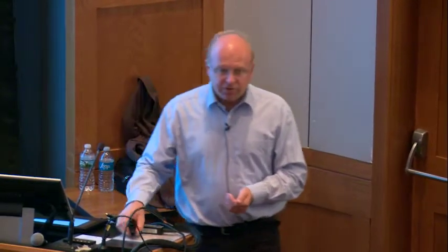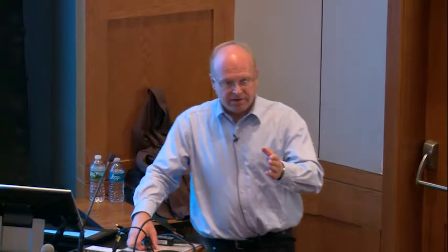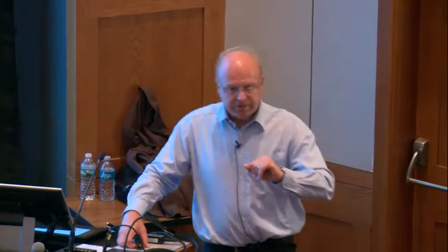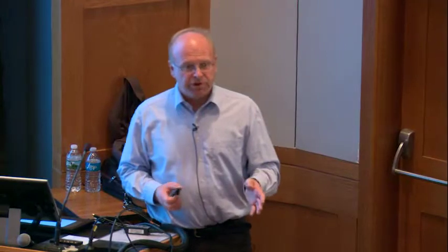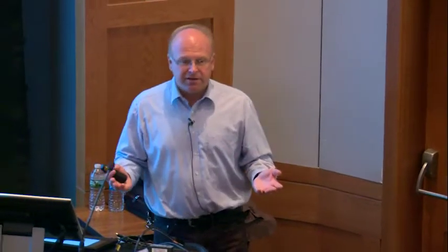It can be reflections, of course, although reflections can be handled. You just take one exposure without the particles and store that, and then you subtract it from each of the images. You correct for the background. That means that your reflections should not saturate your camera. It's very important. If you have saturation, then this doesn't work anymore. So there are more than one reason why it could be. But these are two examples, yes.